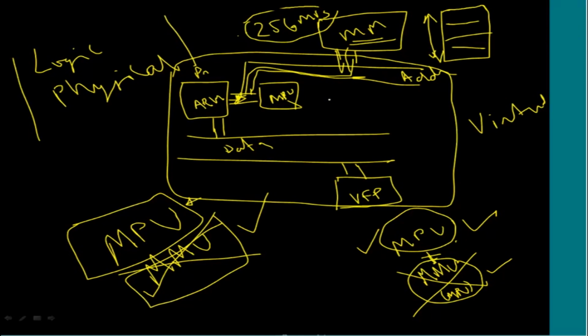There is no MMU to translate to another unit, so that the virtual memory space may be bigger and the actual physical memory smaller. That option is not there. So we have to keep in mind that when we talk about the MPU in isolation, there is no MMU present in the system and no virtual memory concept here. We can build a system like that also.